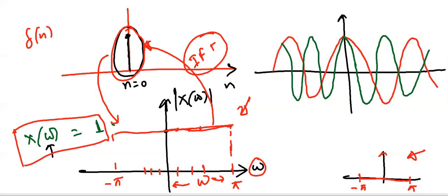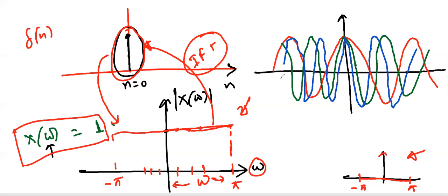Do you need a 3 Hz signal? Yes, the answer is again yes. And what should be the phase? That should be 0 again. So it should always start like a cosine signal. And if you draw like this and keep doing it for infinite time, then what will happen? You can find that only at this portion you are adding the things. Everything will add up there. And for any other portion, they will subtract from each other whenever you are adding all those signals together.